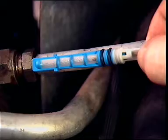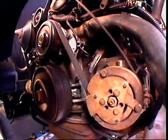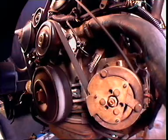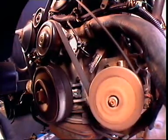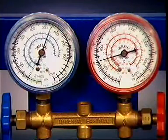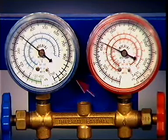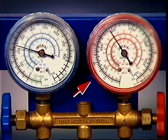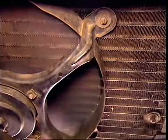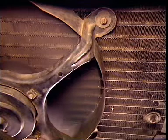operation. When the air conditioning system is switched on, an electromagnetic clutch is energized on the compressor drive plate, and the compressor is driven by the engine crankshaft. Vaporized refrigerant is drawn from the low-pressure side of the system by the compressor. It is discharged from the compressor as a high-pressure, high-temperature vapor and flows to the condenser where it is cooled by the air flowing across the condenser coils and fins.